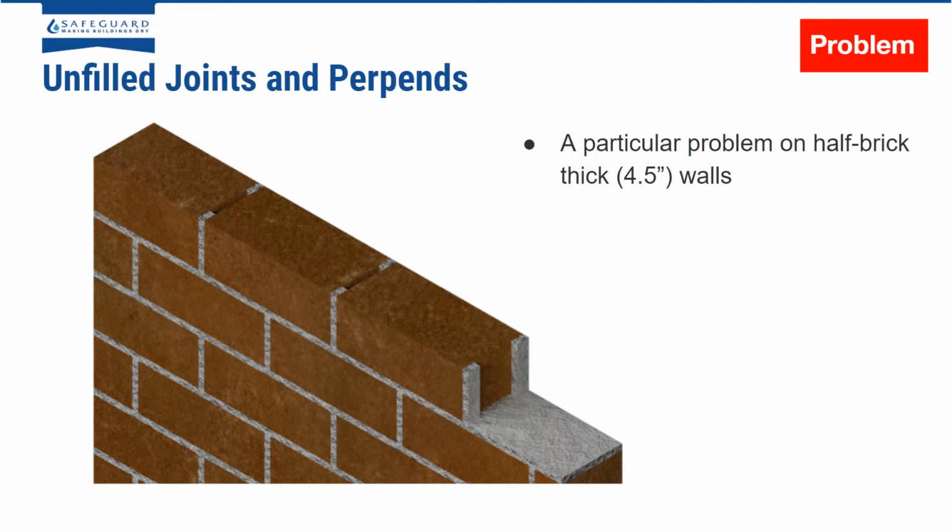Unfilled joints and perpends. It's a very common problem for single skin walls where the mortar lines haven't been completely filled, and so where any moisture does get in, it can then start to collect and also start to penetrate to the inner surface.